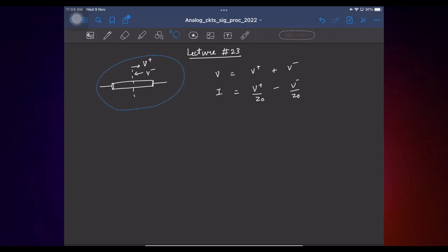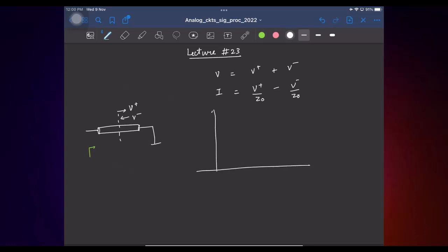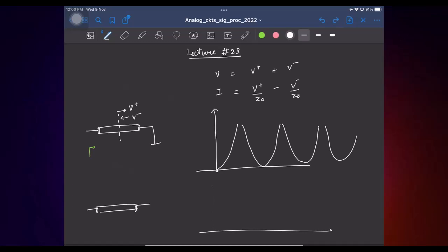Also, last class we saw that if you have a short circuit on one end of the line, looking into the other end, how does the input impedance look at low frequencies? At DC, yeah, it's a short. At low frequencies, close enough, it behaves like an inductor, so it actually does something like this. And this has multiple resonances. Similarly, if you have an open circuited line, again at DC it behaves like a pure open, and again you have these multiple resonances.